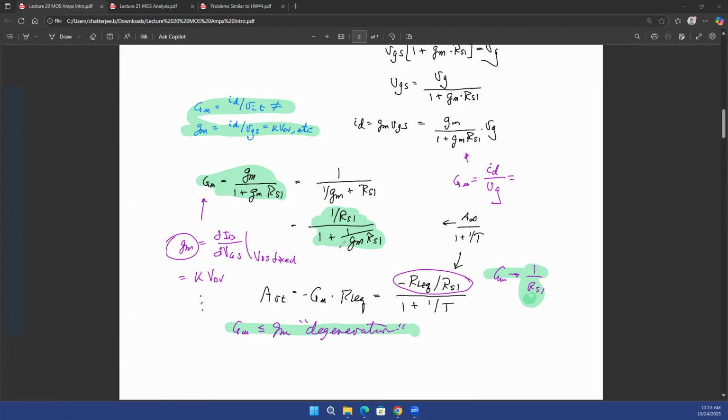Yeah, having a small gm of 0, of course, means that if the MOSFET does not have any transconductance, you cannot expect any transconductance of the circuit, right? Because the MOSFET converts the voltage to a current. If that phenomenon is not present, you cannot expect the input voltage to be converted to output voltage anyway.